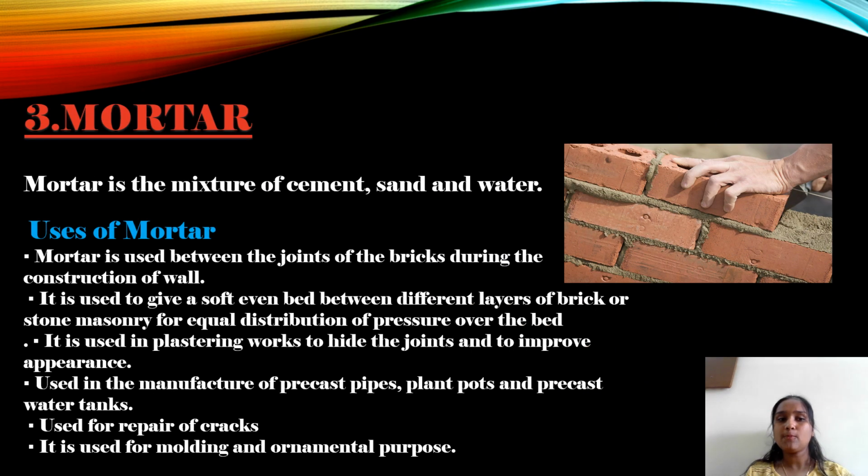Next material is mortar. Mortar is the mixture of cement, sand and water. Uses of mortar are: mortar is used between the joints of the bricks during the construction of walls. It is used to give a soft, even bed between different layers of bricks or stone masonry for equal distribution of pressure over the bed.